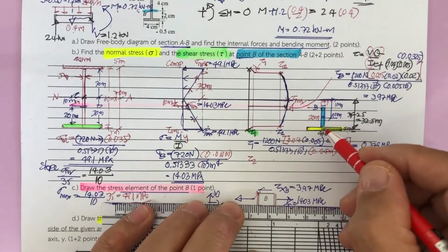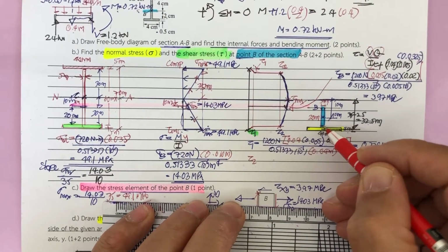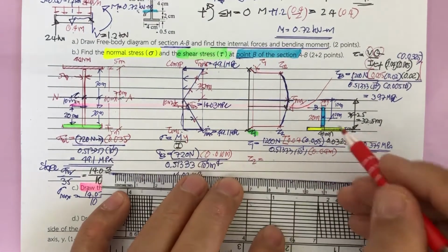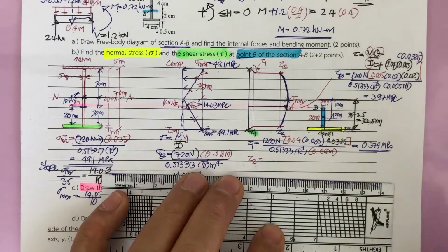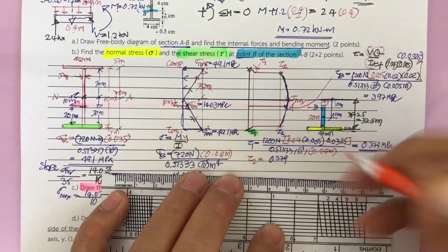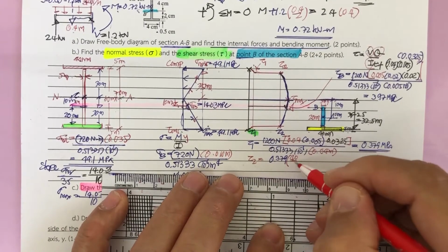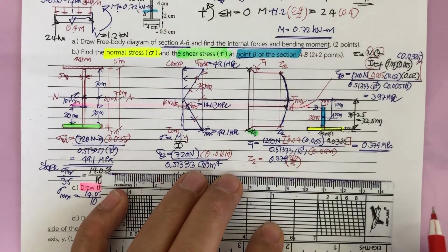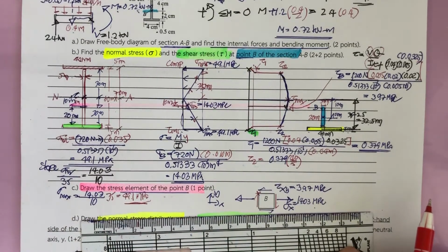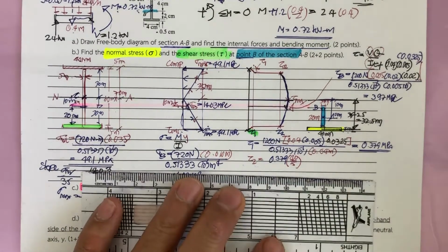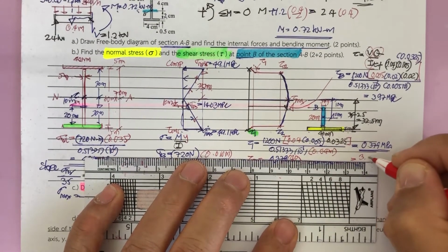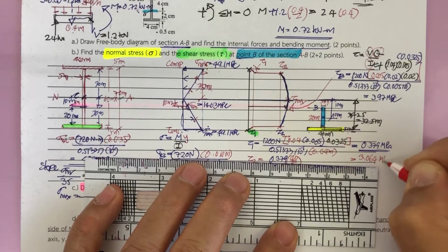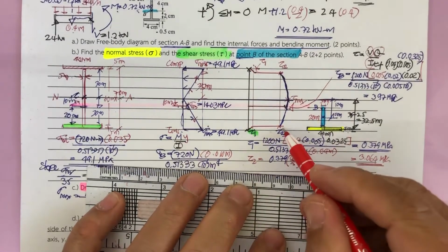Okay, tau sub 2 is based on the width here. And you can see the ratio of the width. This is 40. This is what? This is 5. Okay, you may see this can be computed by 0.379 and then times 40 divided by 5. You can compute this one easily. Tau sub 2 is going to be 3.064 megapascal. That is 8 times larger.